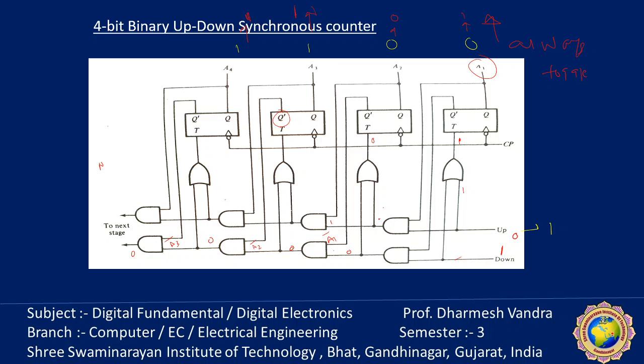The output of the upper AND gate is 0 by default, because one input is 0 and that always remains the same. Now it depends on the lower stage AND gate. So here the down input is 1. The present state we are considering is when all the previous stages are 0, and only then it will be complemented. Okay, so let's take the example where 1 0 0 is the present state